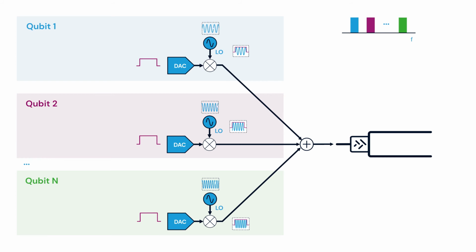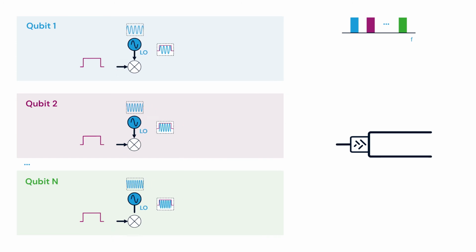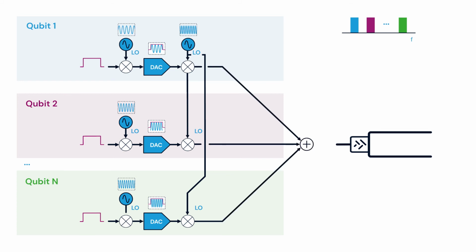However, having n different microwave oscillators in the same system can become a nuisance. So it's much better to use different oscillators for each of the qubits, but also have them oscillating at a lower frequency. Implement them in the digital domain, as shown here, feed each of them to a digital multiplier, and then to the digital to analog converter, and multiply the result by high-frequency microwave oscillator signals. In this way, we can sum and send them through the microwave coaxial cable. By doing so, we obtain exactly the same signal, and we only have one high-frequency microwave signal that needs to be distributed in our system.